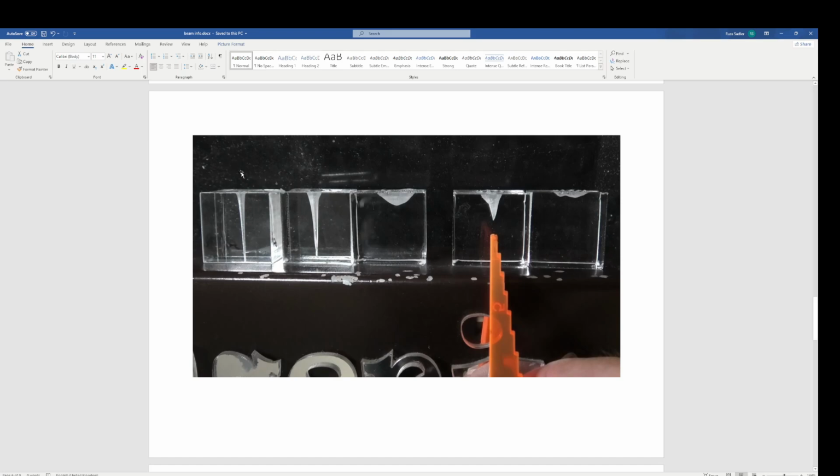And if you can concentrate the light energy into a very small diameter, we can do damage very, very quickly, as you can see with this first image. We pierced through 25 millimeters of acrylic in 4 seconds. Make the diameter bigger, and the rules of Gaussian distribution say that we will not be able to damage the material as fast. And this one took 8 seconds because it's a larger diameter for the same power.